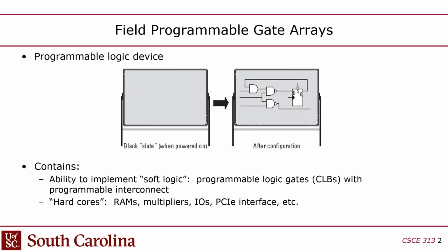And you can do that with the Atmel chip, but only through that reset pin, and it's almost like a secret capability. But if the board doesn't allow it, because they soldered a capacitor on that pin, the capacitor will not allow you to. You can't get the bits through. Yeah, because it acts as a low pass filter. Even if you try to send the bit stream in, the capacitor will take all the edges out of it.